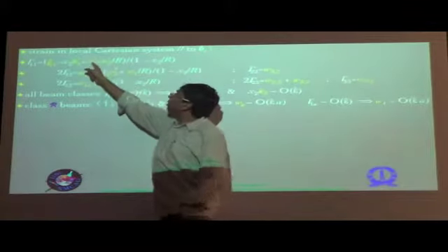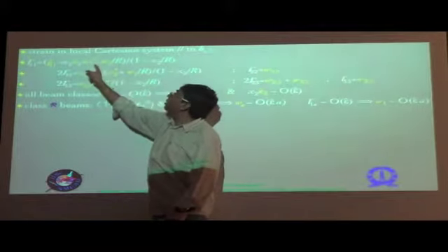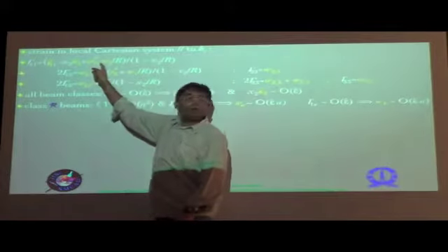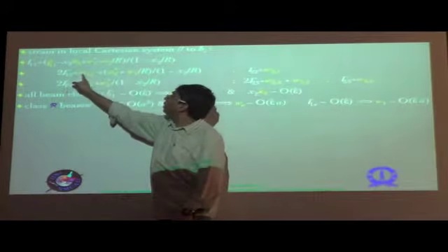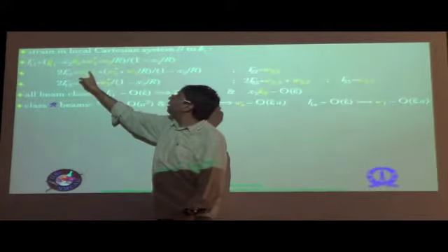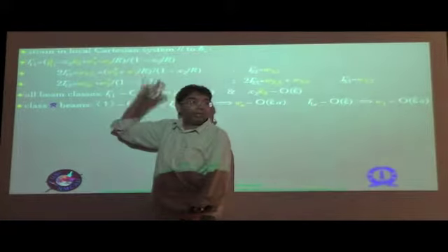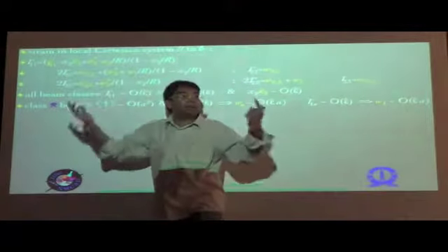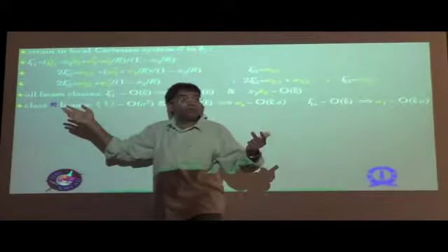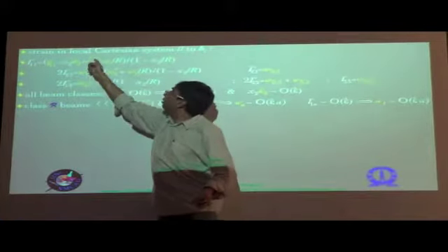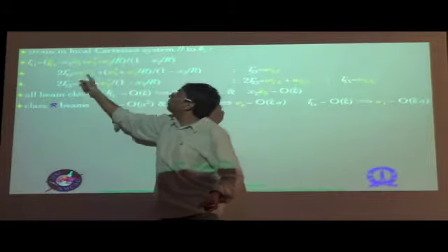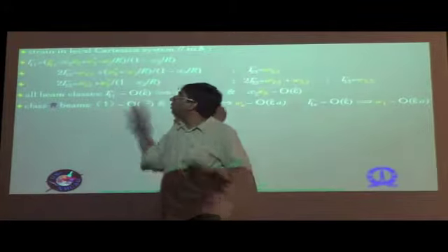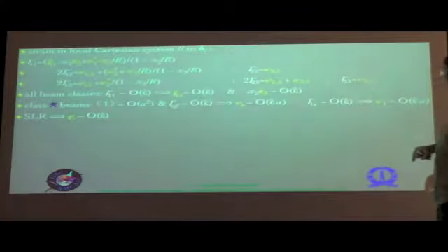We are not taking this because if we take this as order of epsilon hat, W1 would become epsilon hat times L, and when we go here, it would become epsilon hat times L divided by A. And L divided by A is a large quantity compared to unity, and therefore this term would contribute something bigger than epsilon hat, and therefore cause the failure of the material. So we cannot do that. Instead of looking at that term, we're looking at these two terms to get the order of magnitude of W1, very similar to what we did with W2 and W3. So the out of plane warping also turns out to be order epsilon hat times A.